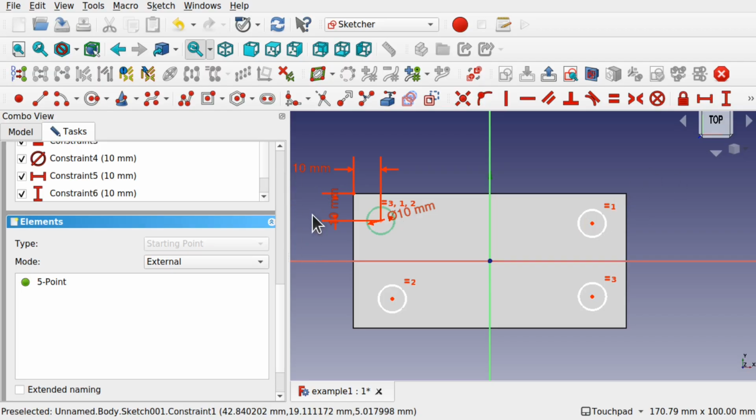So we want least datum constraints. These are called datum constraints because they've got data added to them. The least datum constraints are a lot more easy to control, and that makes our sketch a lot more neater. To put these in line with each other, we're going to use the horizontal and vertical constraints.